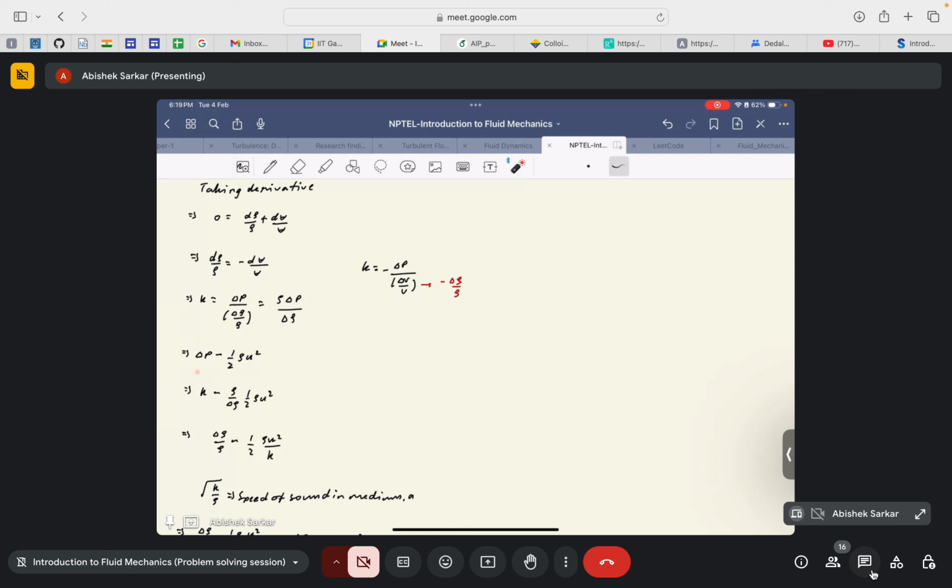So now there is again one consideration here. For most of the flows that we discuss in our course, the pressure would vary as the kinetic energy. So again there is a concept of taking the characteristic length scales. In fluid flows we need to know how the parameters vary. For example, as I mentioned in the previous class, for defining the Reynolds number we need to find the characteristic length scale of the flow. If this is the flow through a pipe, then the characteristic length scale is the diameter of the pipe, not the length of the pipe.